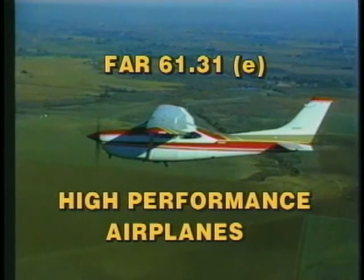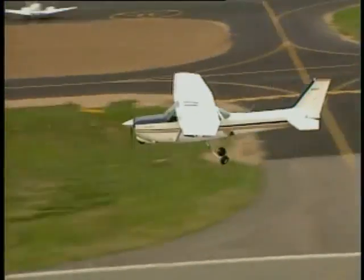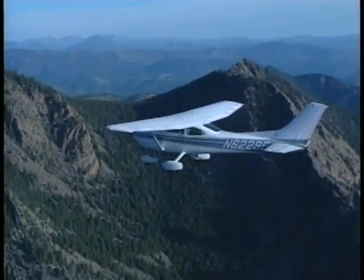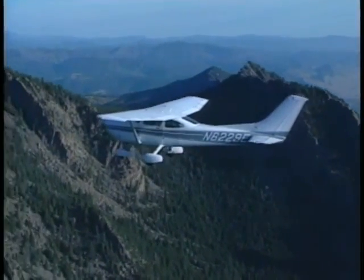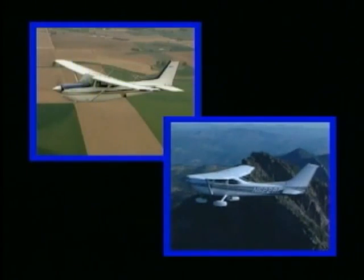An endorsement is required to act as PIC of an airplane that meets either of these specifications or both. For example, if the pilot receives a checkout in an airplane that has retractable landing gear but does not have over 200 horsepower, a general endorsement stating competency in high-performance airplanes is provided. A second endorsement is not required by the regulation if the pilot then chooses to act as PIC of an airplane that has over 200 horsepower. The reverse is also true. However, it is important to explain to pilots that checkouts in both types of airplanes are highly recommended to ensure comprehensive knowledge of aircraft systems and safe operations.